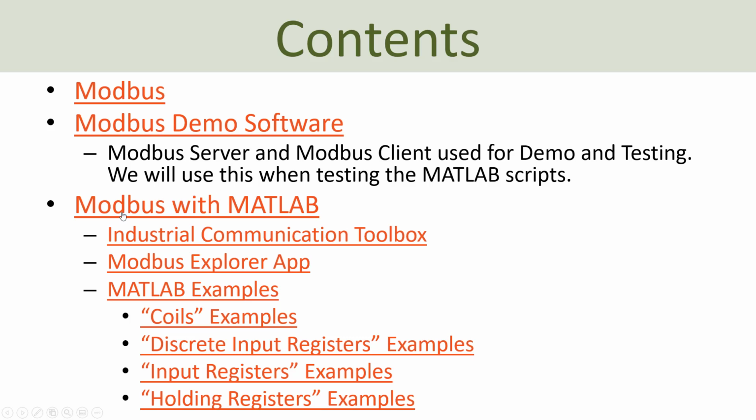Then I will introduce how you can use Modbus with MATLAB and use the Industrial Communication Toolbox. This is a new toolbox in MATLAB that supports Modbus, OPC, MQTT, etc. Then I will show how you can use the built-in Modbus Explorer, which is part of the Industrial Communication Toolbox. Then I will show some MATLAB examples using the different registers in Modbus, namely coils, discrete inputs, input registers, and holding registers.